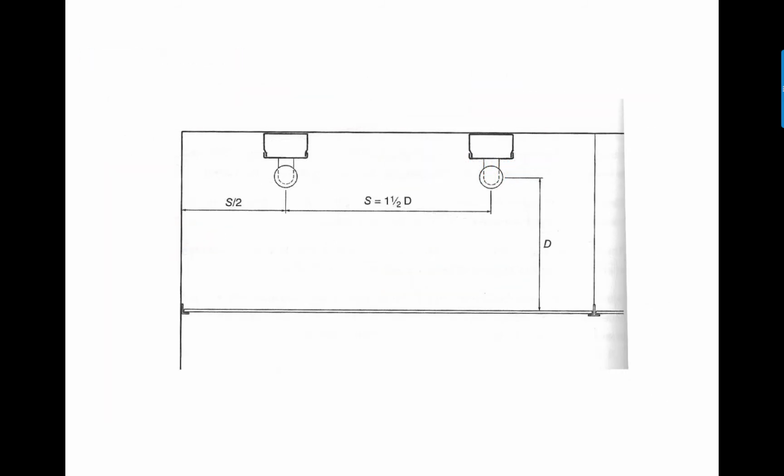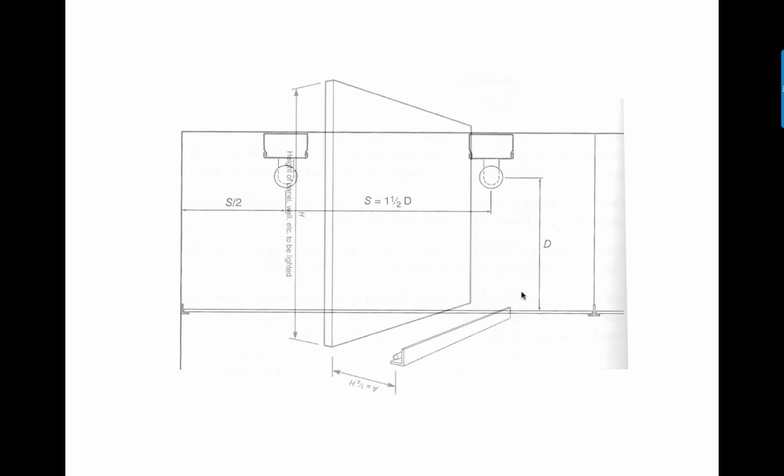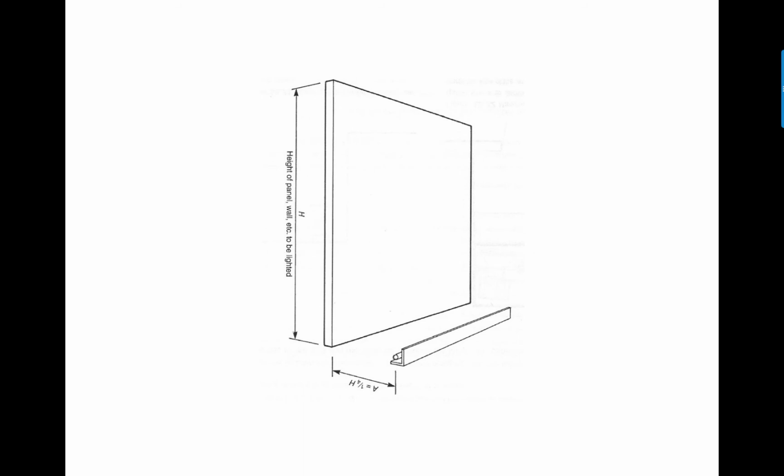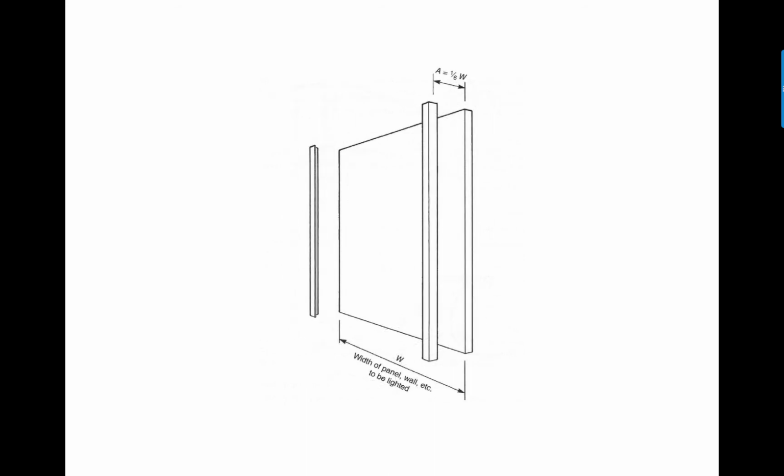So anyway, other types of ceilings that you're going to run into, just a few rules of thumb. This is a luminous ceiling where you just sort of line up a lot of fluorescent lights. And again, this is the most common setting. And fluorescent tubes are still fairly popular. Again, they are efficient, and if you're not looking for great color rendering, they can be used in any number of spots for different effects. Here's a wall wash from the bottom or from the side. These kind of look silly, but that's what they are.